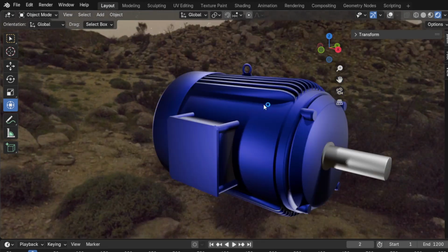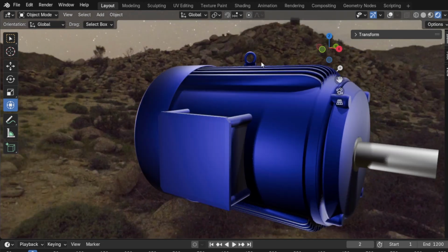Right here we have the chassis. Normally it's painted blue. Sometimes they can be different colors, but it seems like the Baldor Alliance motors are typically blue. And you have the shaft right here. This is the business end that does all the heavy lifting, and it rotates whatever you're wanting to rotate. And you have this little hoist right here, and I definitely recommend using these if you have a large motor because these things are really heavy. You can hook a come-along, a chain, or a hoist to them and put them in place, so you're not injuring your back.